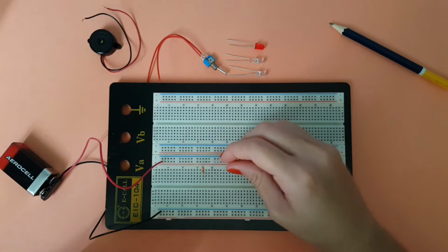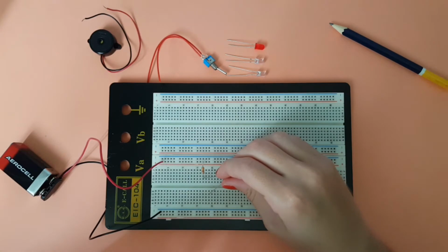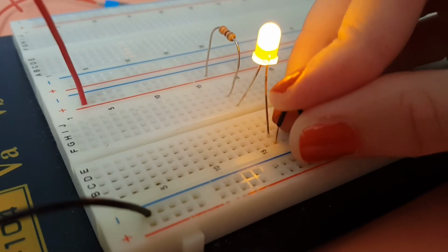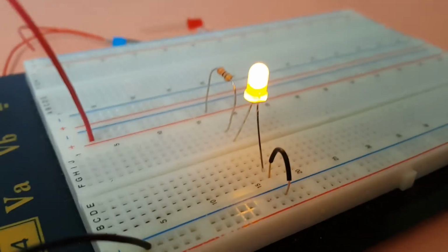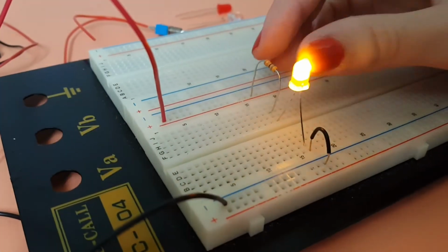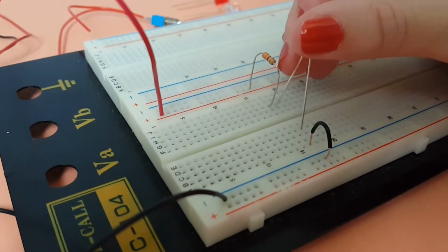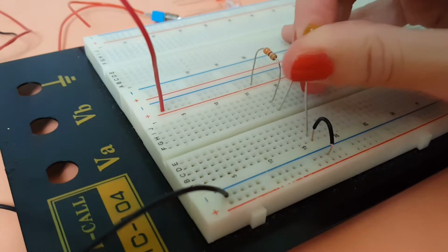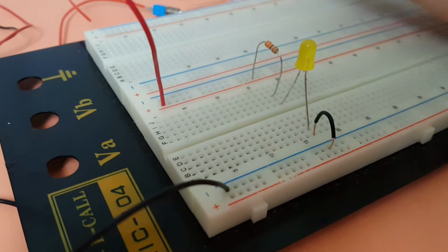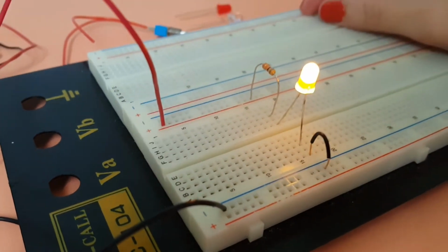When connecting an LED, the anode has to be connected to where the conventional current is going to flow through first. The cathode has to be connected to where conventional current is going to flow out from. Now, if we were to connect the LED the other way around, meaning cathode to the positive side and the anode to the negative side, the LED will not conduct any electricity, therefore it will not turn on. This happens as the LED is made up of a semiconductor material.